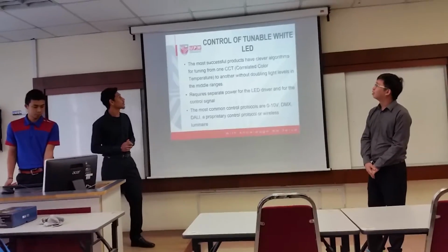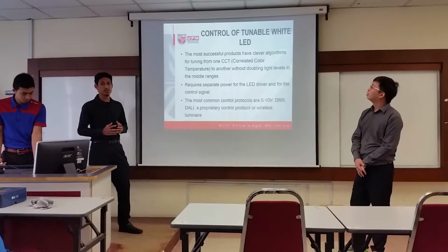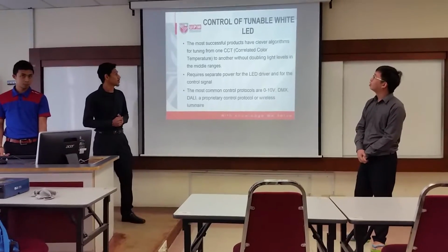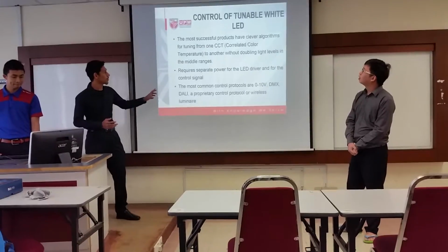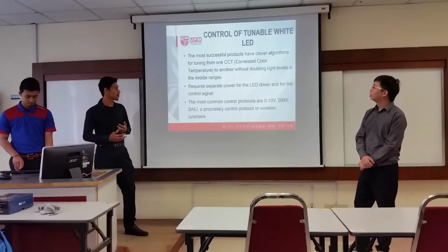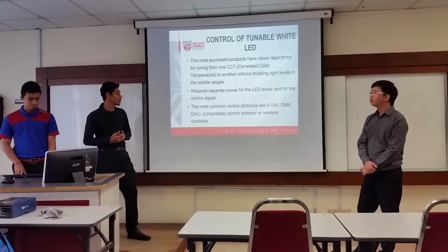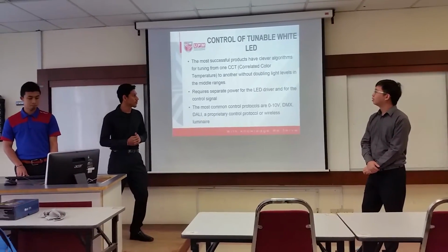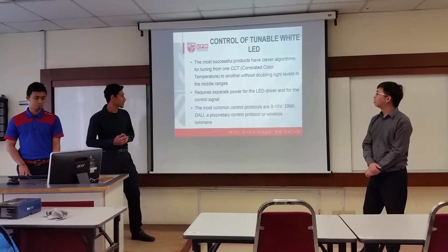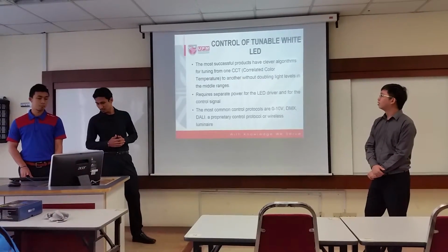The control part is actually very crucial. It requires power for the LED driver and for the control signal, so it needs to have separate power. The commonly used ones are 0 to 10 volt, DMX and DALI.